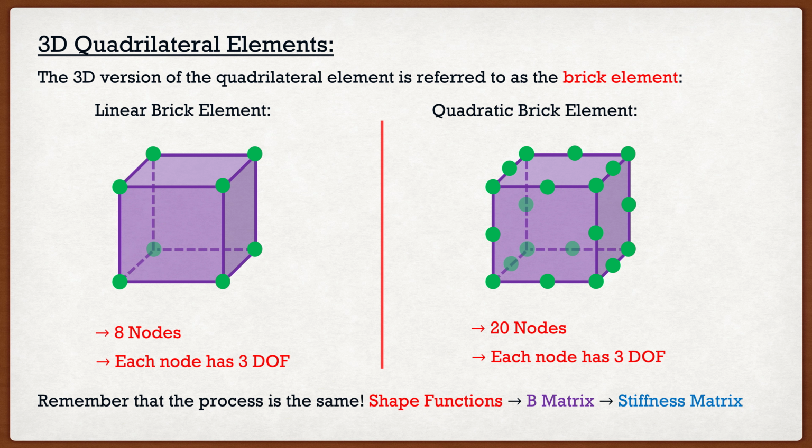Now, I'm going to wrap up by saying this. At this point, we discussed what our general solid elements are, we discussed triangular elements, and now we've discussed quadrilateral elements. Although they seem different, it's actually the exact same process, which is why triangular elements, quadrilateral elements, brick elements, etc. all fall under the solid elements category because the process for them is exactly the same. The equations for the stiffness matrix and the nodal forces are exactly the same. The only difference between these are the shape functions.